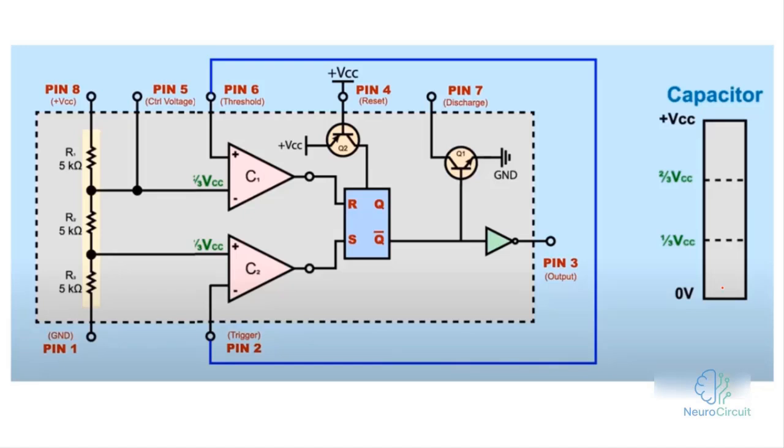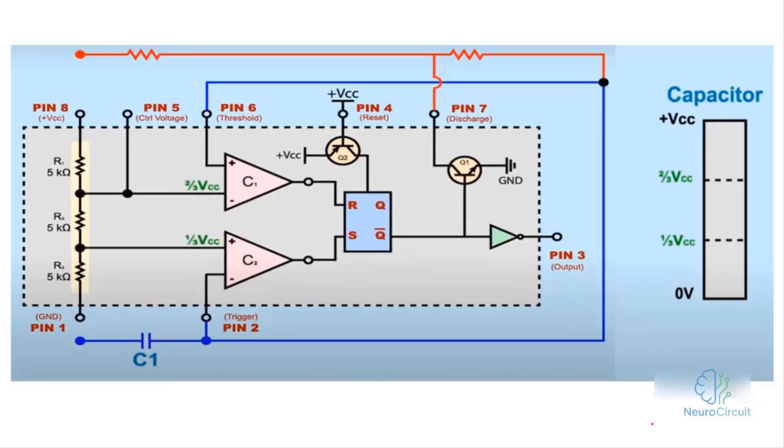Here, just like you might remember, in the first circuit we built, pin 2 and pin 6 are connected together. While I'm explaining this diagram, take a quick look at the diagram on my right. That is, keep an eye on that capacitor as well. In this next diagram, pin 7, or the discharge pin, is connected to VCC through a resistor.